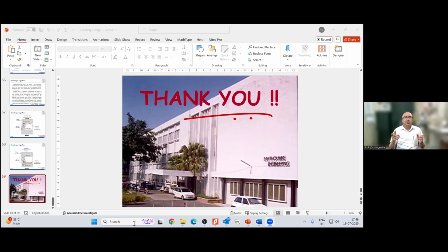Why is it higher? Because there is a slab also, and in the slab we have reinforcement that acts as a flange. So the actual capacity of the coupling beam is larger than what we compute using a rectangular section. So that should be taken into account as per the New Zealand code. Our code does not specifically say that, but it is providing an overstrength factor of 3 for the shear wall. Hopefully that will take care of this also. Thank you.